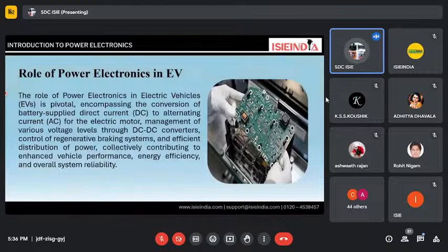As I mentioned, in the controller we have a throttle. Along with the throttle, we have a brake cut switch, auxiliary component connections, and anti-theft system connections. Along with that, we have a lot of wires for peripheral devices, for CAN communication, and for VCU connections. Every different wire runs with a different voltage. So the controller itself has a DC to DC or DC to AC converter in itself.